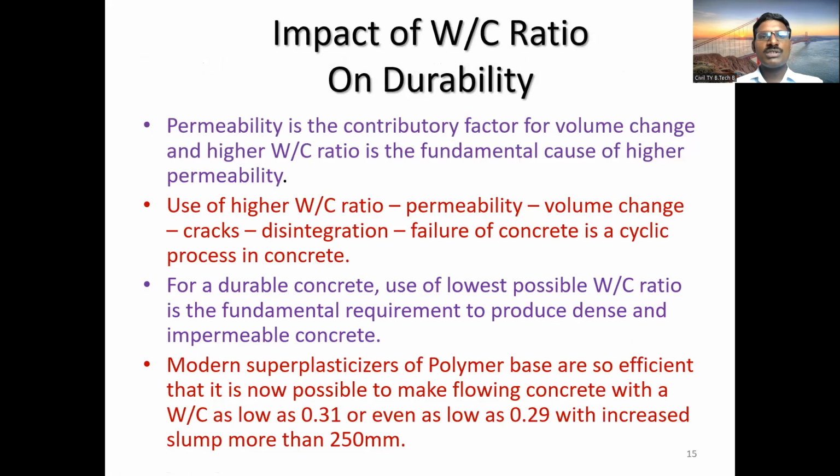So, the impact of water cement ratio on durability. A very important factor is the water cement ratio, and it affects the workability and finally the strength and durability. So what is the impact of water cement ratio? It is a contributory factor for permeability and volume change, and a higher water cement ratio is a fundamental cause of higher permeability.